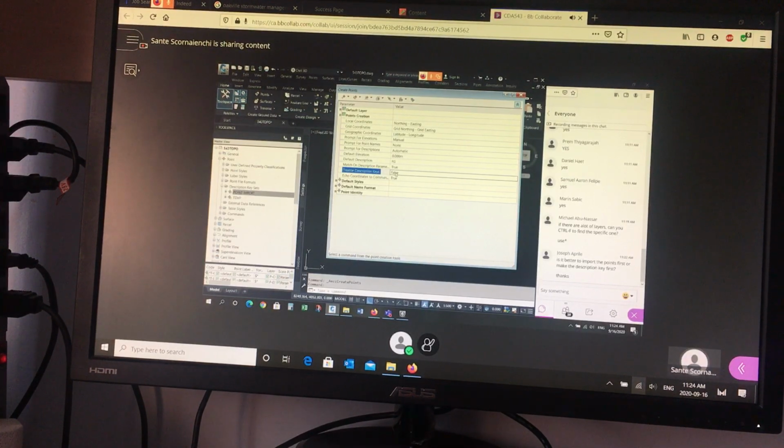The language is kind of funny. Instead of disable description, it should just say description key, and then where it says false, it should say enable or disable. So the language is kind of silly. That's how it works. So if you want the description key function to perform, you have to set this to false. Okay, so that's the one thing to be mindful of. More about this during the import when we actually get to step number 4. Okay, we're still in step 1.